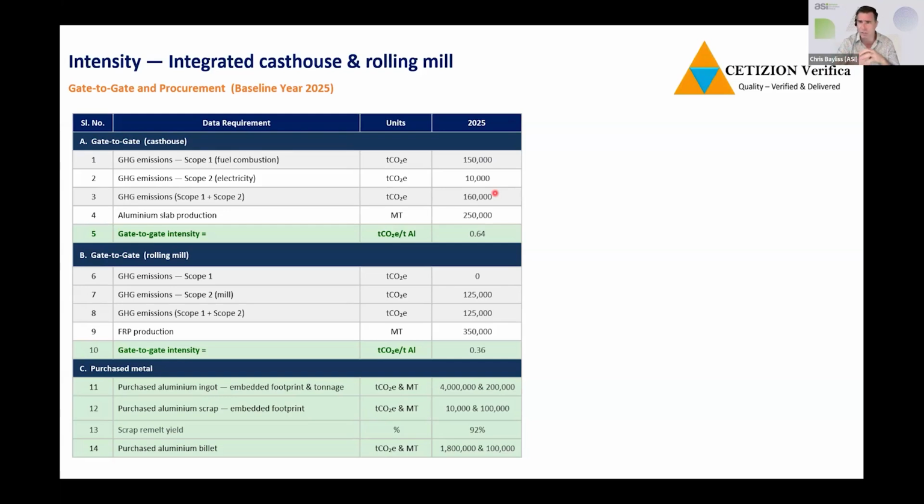But the scope 3 emissions come through in the procurement of aluminium, scope 3 category 1, as Ganga mentioned for foil. Here you'll be using cold metal inputs to your cast house, and that may be primary, some kind of mixed remelt ingot, or scrap. So the treatment of scrap is a thing to consider in the midstream, and how you allocate emissions to it. Often people use a cut-off approach, allocating 0 emissions to the scrap input, and so that has to be mass weighted with the primary input into the cast house.